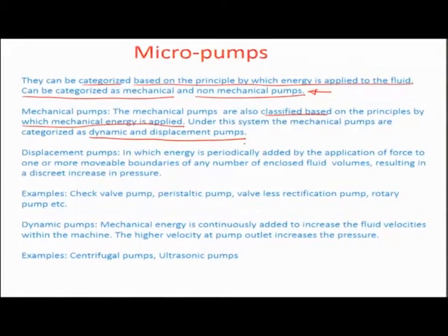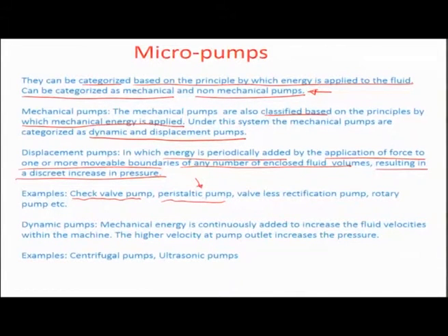The displacement pumps are one in which energy is periodically added, by application of force to one or more movable boundaries of any number of enclosed fluid volumes, and this results in a discrete increase in pressure because of which a fluid is forced to go out. Examples of displacement pumping could be check valve pumps and peristaltic pumps. I am going to talk about this in great detail to design them. Then the valveless rectification pumps, the rotary pumps, and so on and so forth.